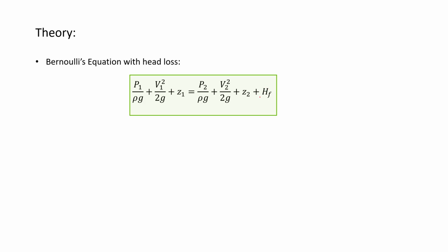But if there is friction, you can simply modify this Bernoulli's equation to get the estimate of your head loss due to friction. So here before we did not have this term when there was frictionless flow, but when there is some friction, we say that maybe this friction eats up some of your energy from going from junction 1 to junction 2, and that if you add that lost energy on the right hand side, you again recover this conserved quantity. So this is your head loss, let's say due to friction. Your velocity head would be 0.